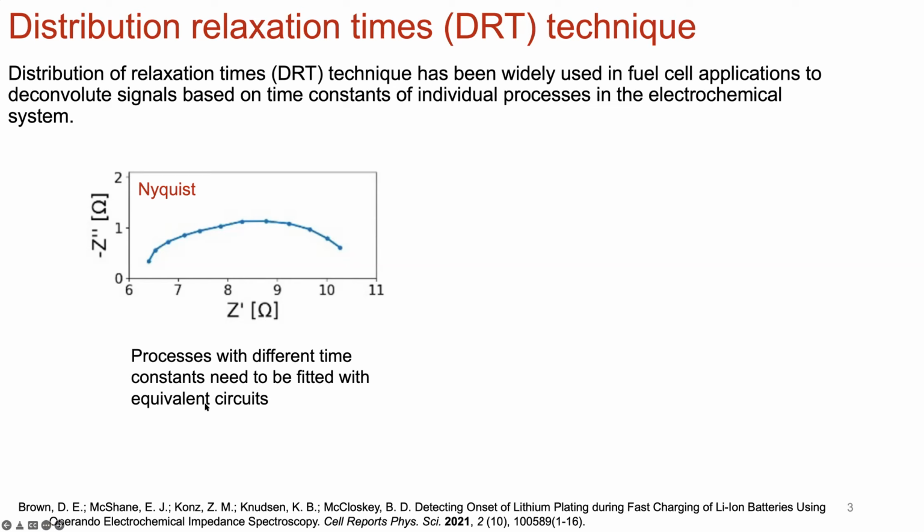And so the typical impedances that we would try to track to see is SEI, what are these individual processes? Is SEI developing? Is it growing? Is it changing over time? The answer is yes, but how is it changing over time? How is the impedance changing over time? And what does that mean for a cell's ability to fast charge?